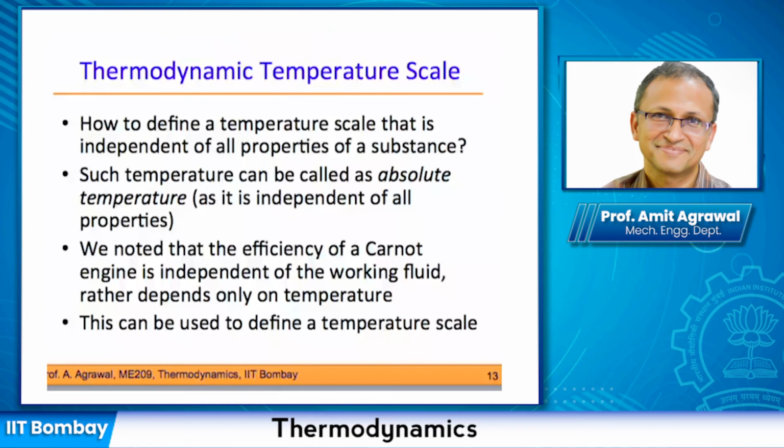So we wanted to get rid of that, saying that we are not involving any substance here. We are only involving a Carnot engine whose efficiency somehow we know. This is always going to be an iterative process. We define a certain temperature scale, and then based on that we see if we can have a Carnot efficiency which is always this number. We can of course check it by taking different temperatures. Of course, Carnot cycle is an ideal cycle; it can never be constructed. But still it turns out to be a more useful definition, because we are not basing anything on the properties of a substance. We are relying on a different idea, which is the efficiency of a Carnot cycle. That's how I would answer that. Okay, sir. Got it.